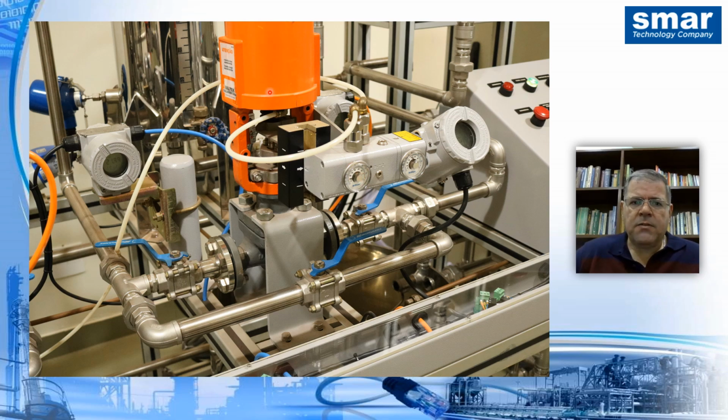Here we have the valve. This valve is a linear valve. As the valve stem operates, a magnet will be present, which will move and create a magnetic field, which via a Hall electronic sensor will detect the physical mechanical position of the valve. The Hall sensor will send the information here to the positioner's electronics, and it will confirm if this information corresponds with the control data it receives.